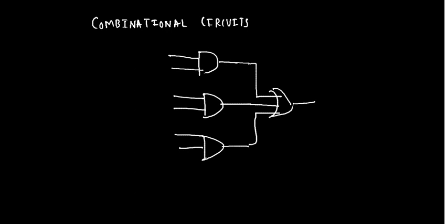The other type of circuits are called sequential circuits, where memories are involved. It may happen that at one time instant the input is 0, and I take into consideration the previous output, say 1, and give it as feedback to the input. I am taking into consideration the feedback or the stored input.